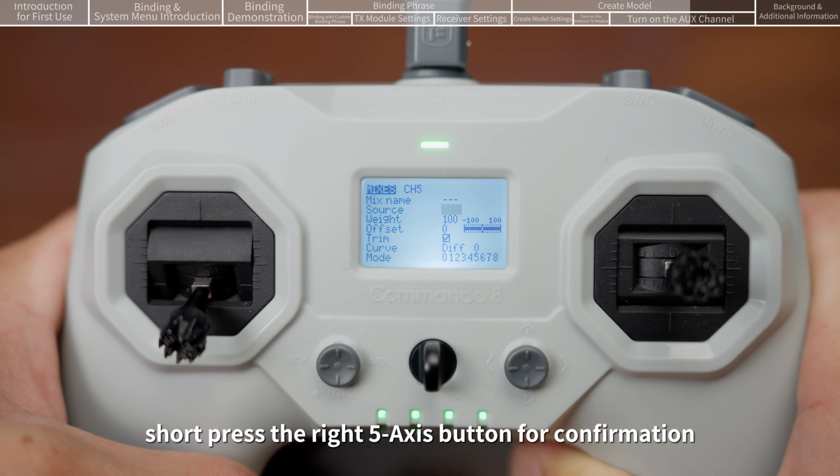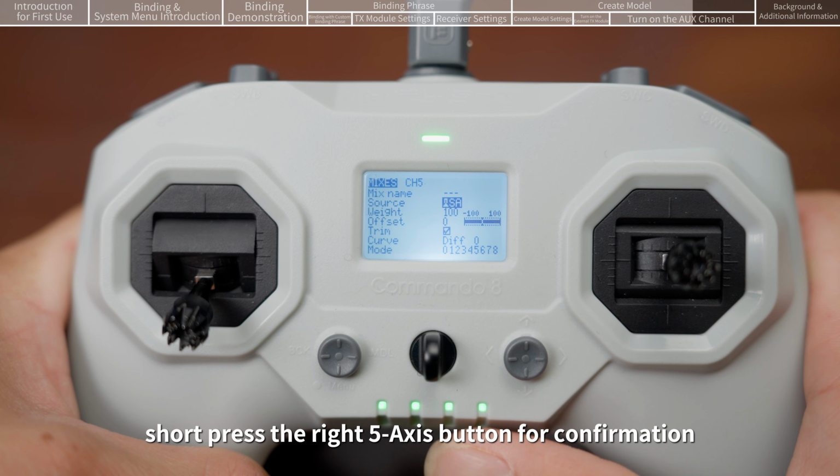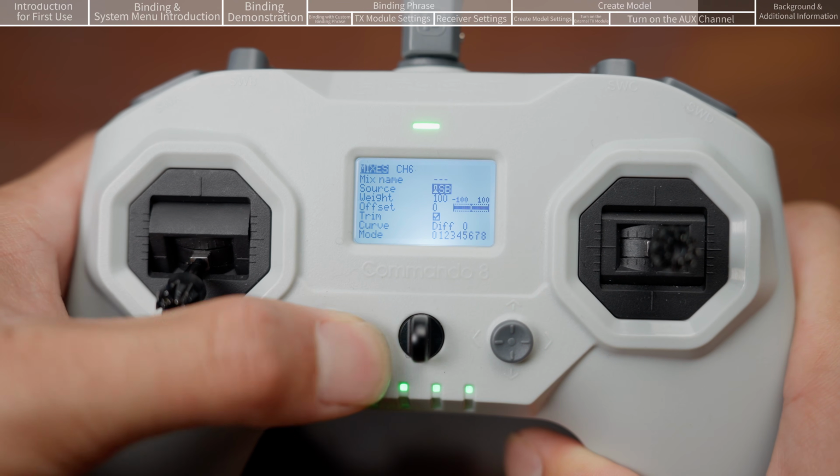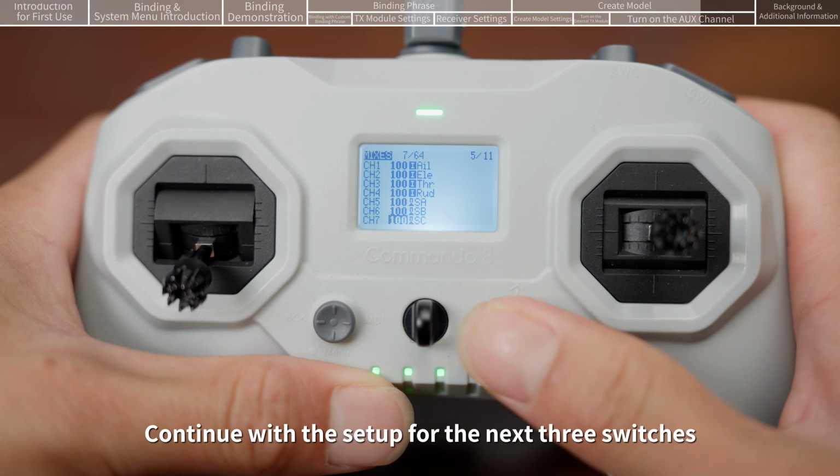After setting, short press the right 5-axis button for confirmation. The position of the first arming switch on the remote controller has now been set. Continue with the setup for the next 3 switches, and so on.